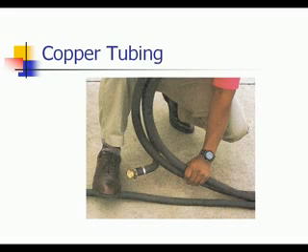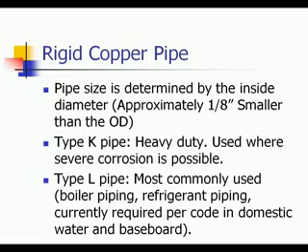Sometimes they're a bundle of thicker and thinner tubing. The thicker side has insulation on it, or Armaflex. This is an example of the line set, and you can actually see the quick disconnects on the end of the tubing. The suction side, or the low pressure side, because it sweats and it's cold, is covered with insulation.